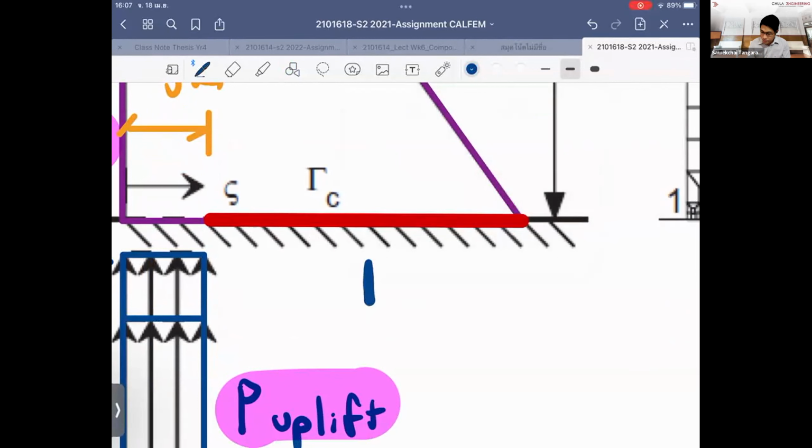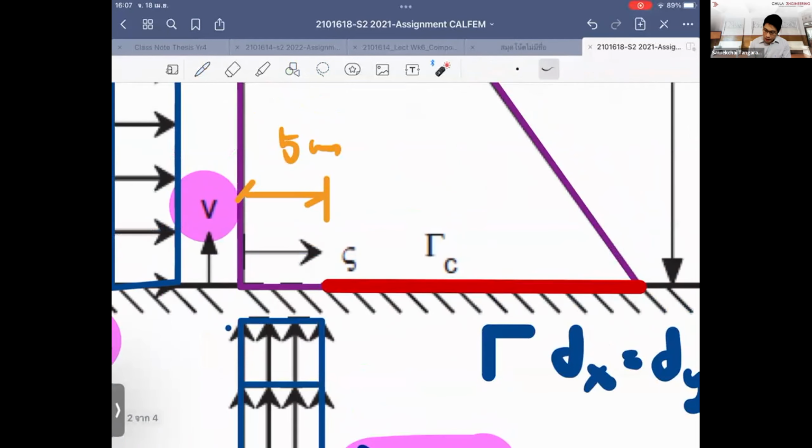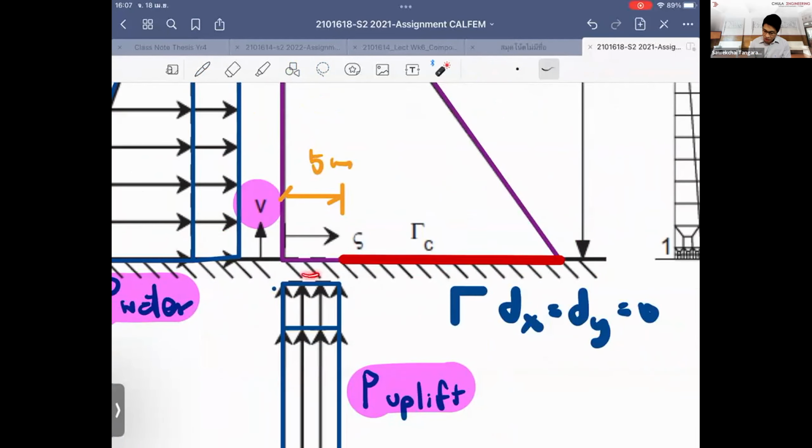When it has been well connected to the ground, what it's telling me is that when I'm looking at the node here, each of the node points is giving me the restraint condition, which is dx equal to dy equal to 0. But the condition at the opening is free. So the degree of freedom at the bottom has been free, so it can open up, right?